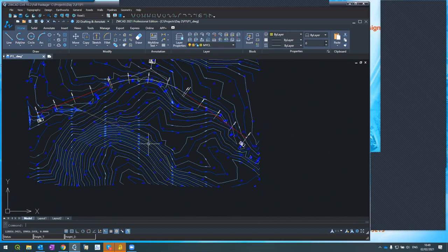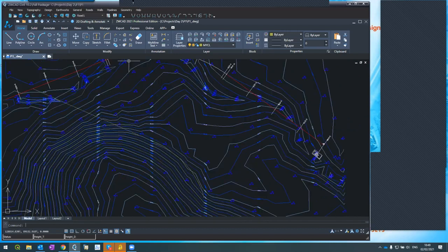How do I do it? How do I connect the two? For this, I'm using the toolbar here on the top. You see this toolbar? We call it horizontal alignment toolbar. And I'm using the many functions here. I'm using something that's called line arc fit clothoid. I have a line, which is the tangent, this one. I have an arc. I want to fit them with a transition curve between them. So which one? Line arc fit clothoid. This is the one, second to the right.